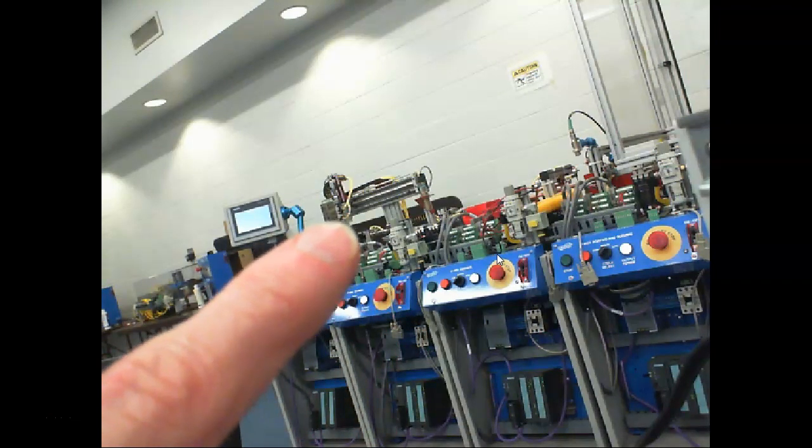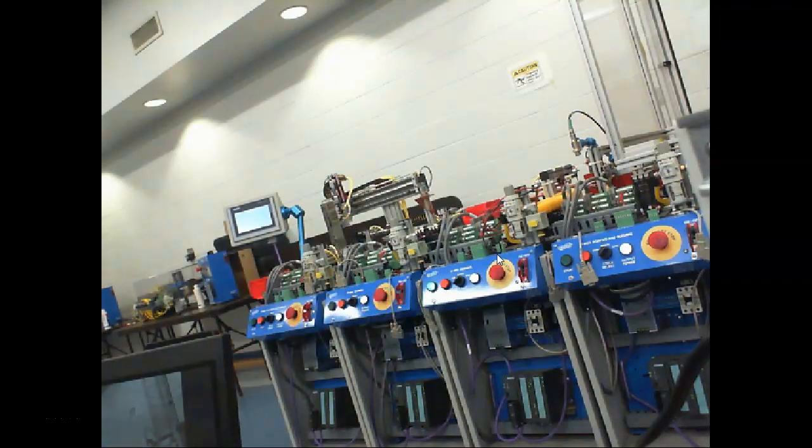This station right here has a suction cup on it, and it's got an analog pressure sensor on it, so we can actually measure the amount of pressure that's generating the vacuum. And we'll look at that. You can actually generate a vacuum from a pressure. It's called a Venturi, and we'll look at those. This is on both these manufacturing lines. It uses a Venturi to take a pressure and convert it into a vacuum.